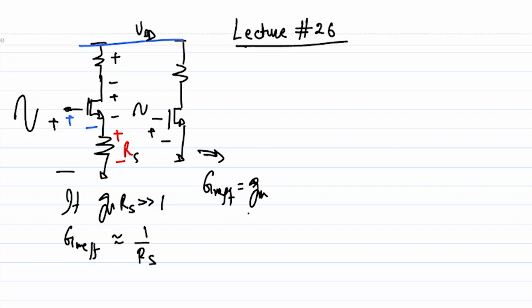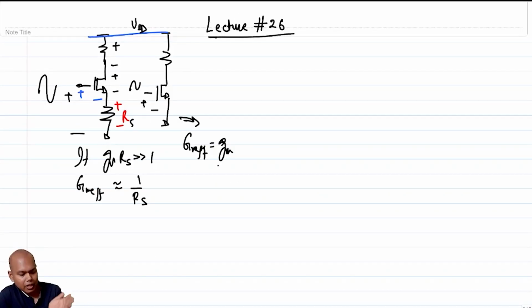So not only are you able to get higher quiescent overdrive, but you are also able to get a higher GM. Granted, at face value it might look like the circuit on the right can have higher distortion, but that statement has to be qualified with respect to the finite voltage supply that we are operating with, right?